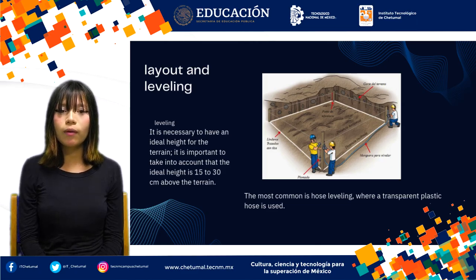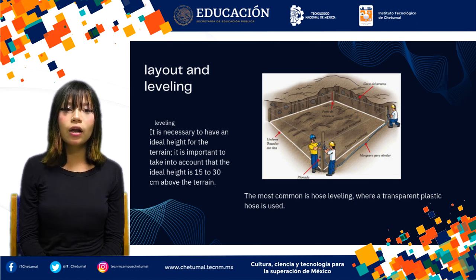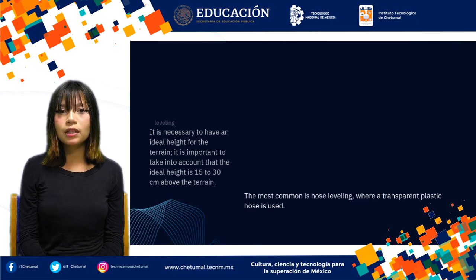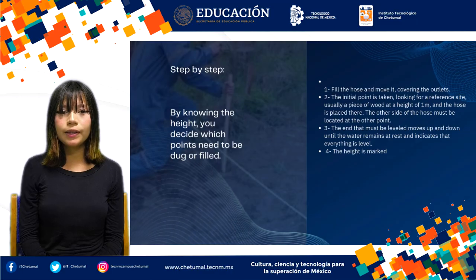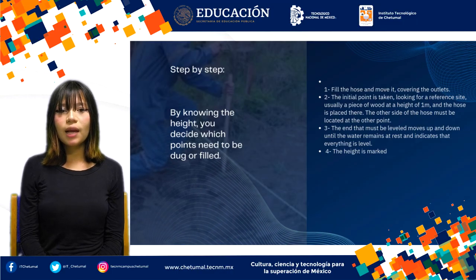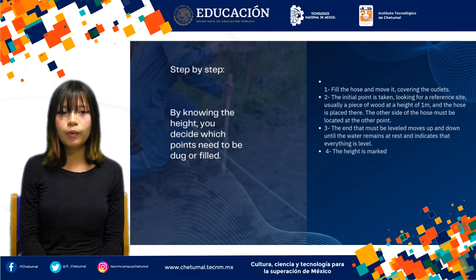Now let's talk about rebar, an indispensable material for reinforcing concrete. Function of rebar. Steel rebar is used for reinforced concrete in structures like columns, beams, and slabs. Concrete is very strong in compression, but weak in tension. This is where rebar plays a crucial role, as it absorbs tensile forces. Types of rebar. Rebars are classified based on diameter and strength. Each type is used for different applications, depending on the loads that the structure needs to bear.